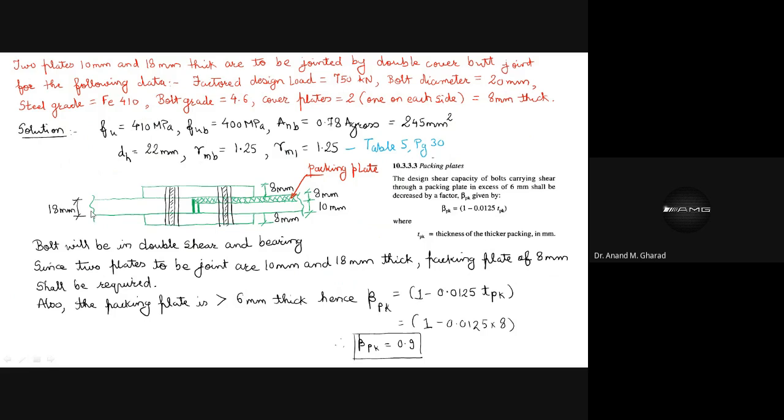Okay, one is an 18 thick plate, and this 18 thick plate is to be connected with another plate of 10 thickness. So you can see there is a gap. Can you see this shaded portion? This is a gap. Initially you can consider this to be a gap, and you are supposed to connect this complete thing with the help of two plates of thickness 8, which will be lying on the top and the bottom of these two plates. So such a connection is to be made.